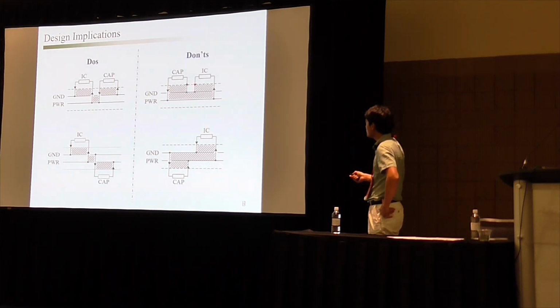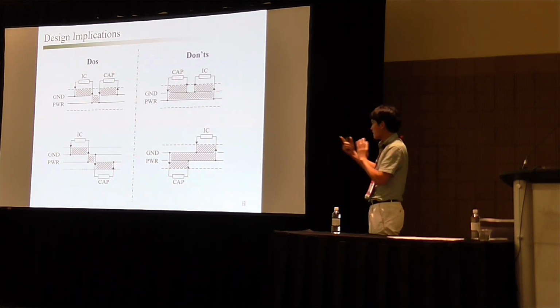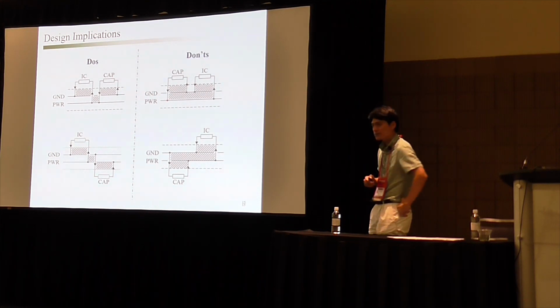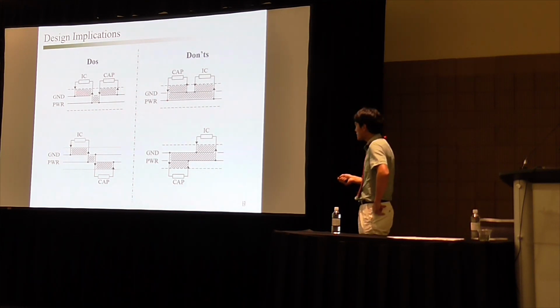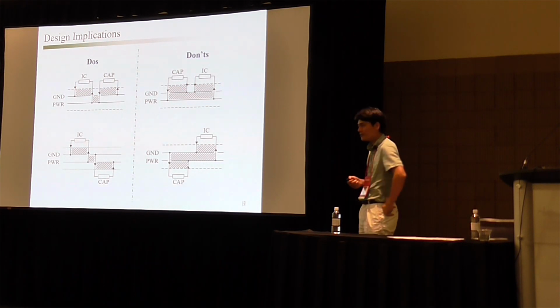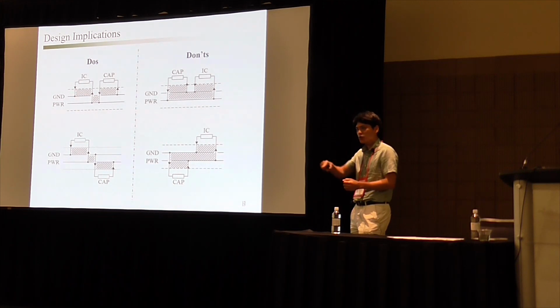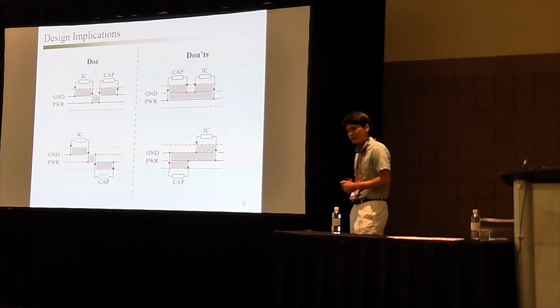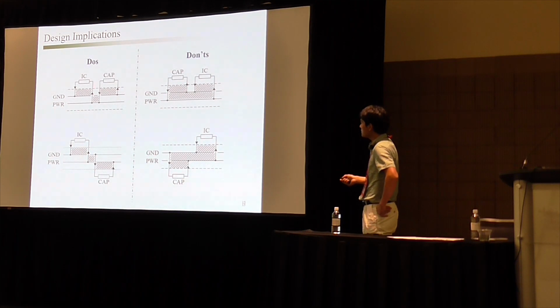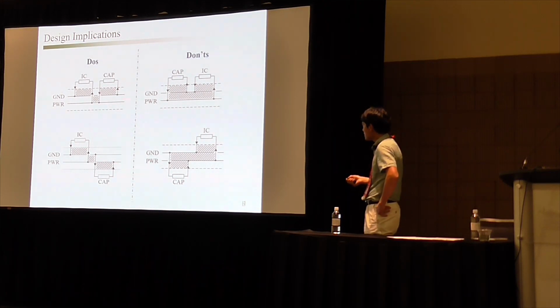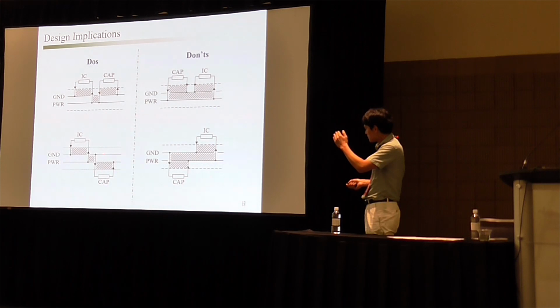And on the right, we put the power via outside of these two components and connected to power on the bottom. As you can see, following this current loop, their area is quite different, right? Again, it's about the current path and the loop formed by this current. So this gives us much less area, so much less inductance.